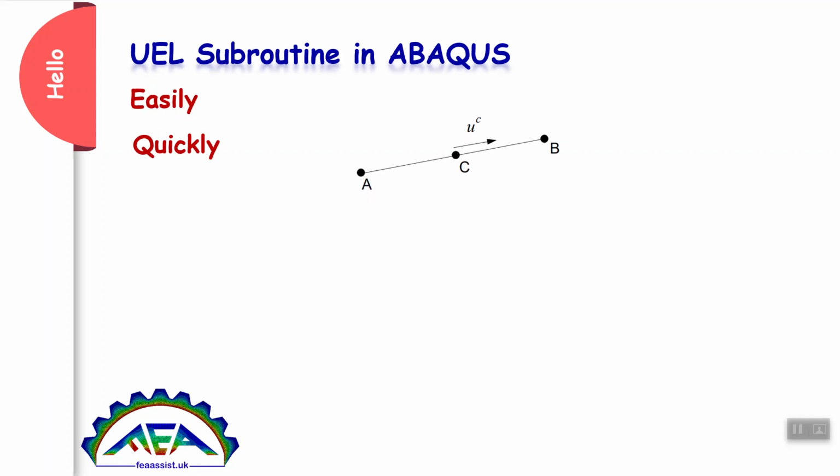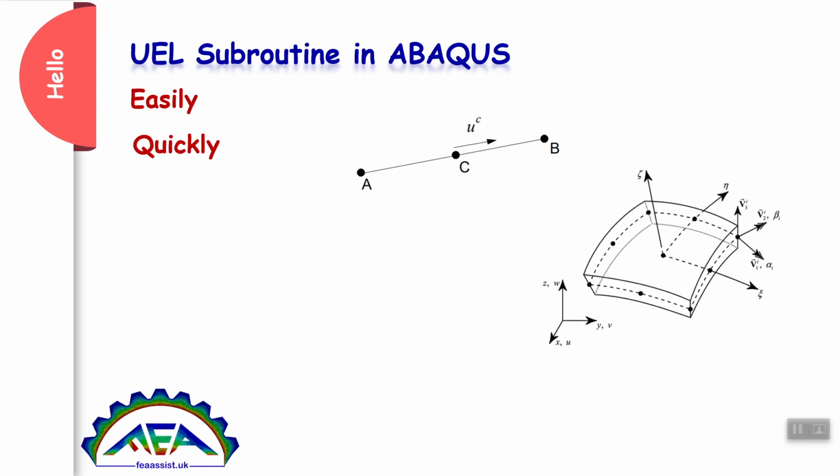Interpolation function can be linear or cubic. You need to define your function in UEL subroutine. For 2 and 3 dimensional problems, it's the same. We need to define a new element with a new interpolation function. To well understand these things, stay with us.